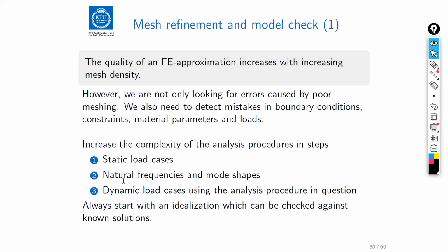And since they are moving in a more general way than the static load cases that we might have started with, apart from giving us a new quantity to test against a known model that we know is correct, it may also reveal, let's say, pieces of your model that are not fitted together in the right way. That is, if some of the internal constraints are not well defined, you might see things that vibrate in ways that they shouldn't be able to. So this gives us a second line of defense, let's say, to find all those little errors that we typically make every day.